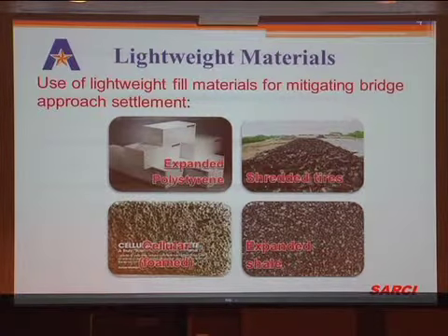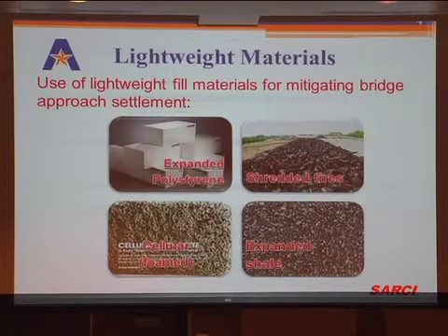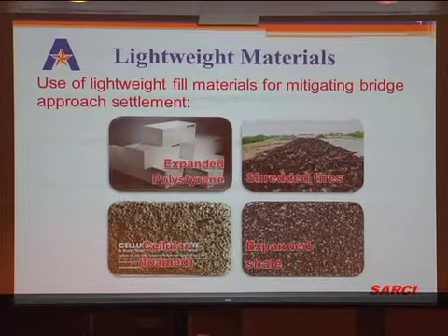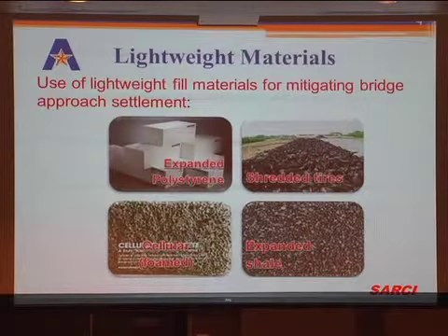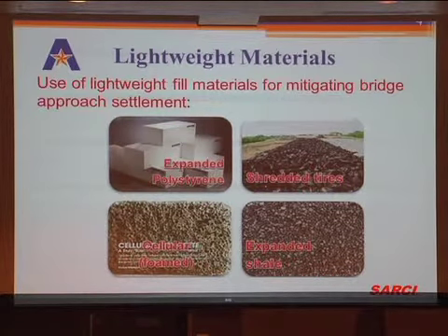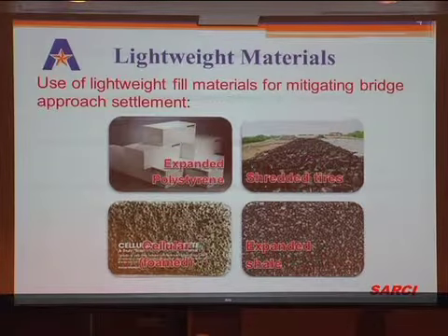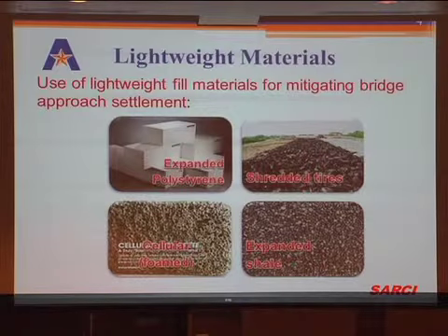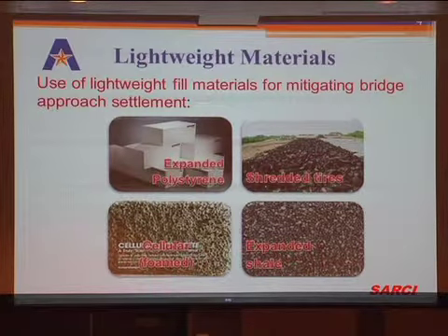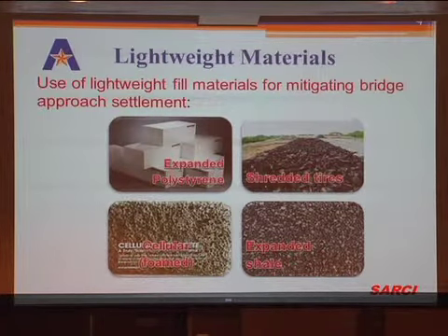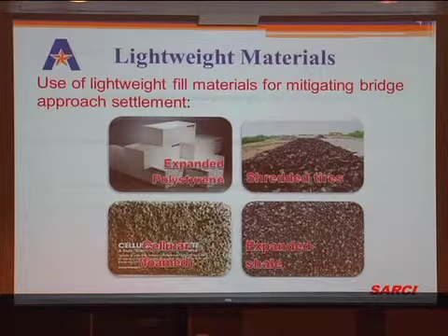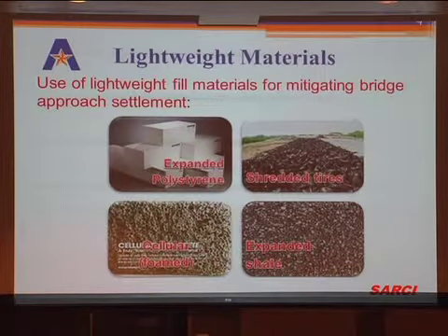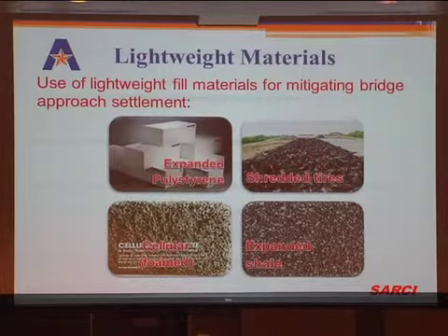And again, that's a lightweight type of material that has been used all over the world in cutting down the settlements. You do have shredded tires. You can mix them with soils, and it can be a good fill material. And then again, cellular foam material that has been used. In fact, last month in Europe, I saw the cellular material that is on the market that they use as a lightweight material. And then expanded clay shale, which we have studied on one of the project sites for State Highway 360, expanded clay shale.